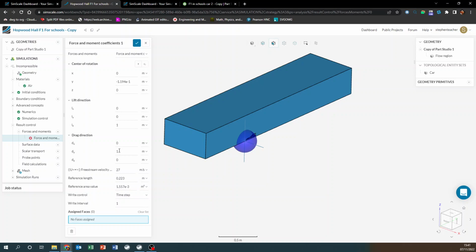for the moment. Right, so we've got centre of rotation. Centre of rotation is often called the centre of mass, so we can do that easily in OnShape. So if you've got an assembly here with various parts, you need to select all your parts. You need to make sure that each part is assigned a material. So if you right click, it says edit material or assign material.